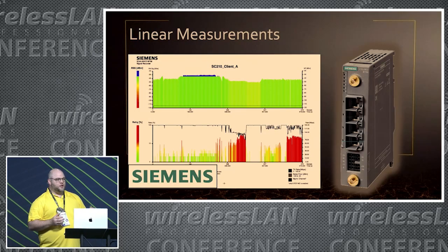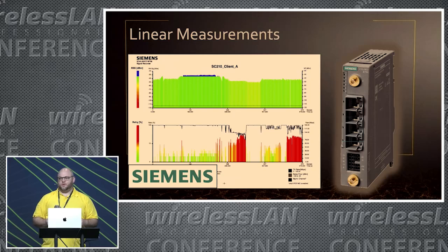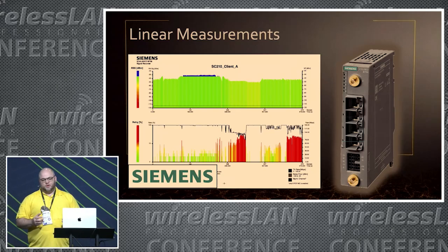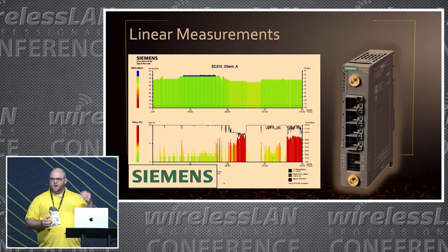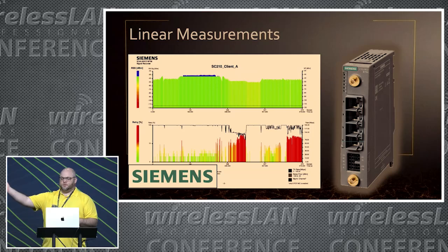And then the backup approach, or the second big bucket of tools that we'd use in these Siemens industrial clients, is the signal recorder feature. And this is real easy. You log into the web page, navigate through a few menus, you configure the frequency with which you want it to report. You start your capture, you run it, you can log out of it, log back in, stop your capture, save the file. You get a CSV, you get a PDF print that's got all that CSV data appended to the end of it.